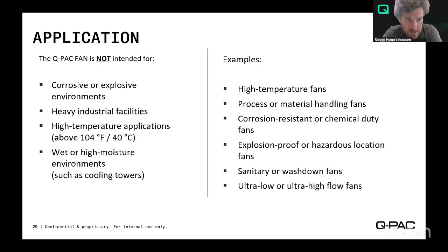But other places, heavy industrial facilities. So this is those situations where maybe you have 30, 40 inches of static pressure. Maybe this is a mining operation or a wastewater treatment plant where you have some massive fan that has to move air for a really, really high heat load or something like that. Also, wet or high moisture environments like a cooling tower may not always be the best application. But again, whenever you're looking at retrofit applications, you want to be aware of the real needs of the customer. Do they need to move air? Do they need reliable airflow? There are always things that come before the recommended application. So just something to be aware of.